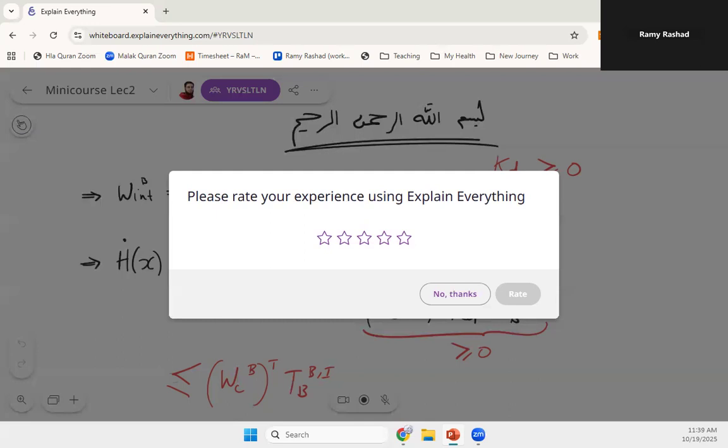No, the non-passivity is because of the controller. With the standard impedance controller, you have the controller, the system and the drone. By drone here, I mean just the rigid body. The rigid body of the drone, the controller of the drone and the environment are all passive, which means I have guaranteed stability, provided that the wall is there.